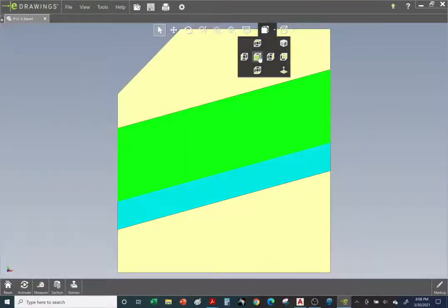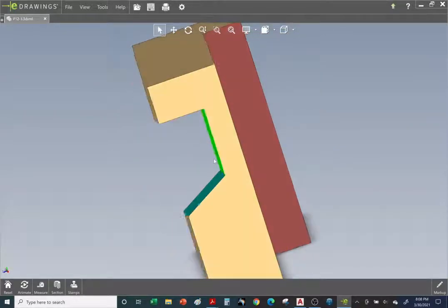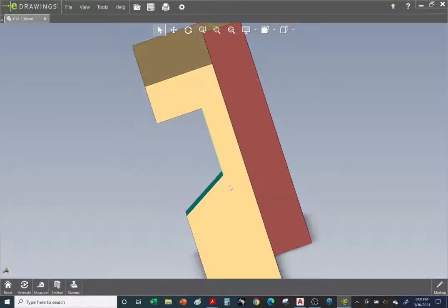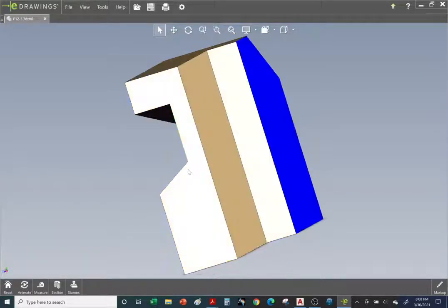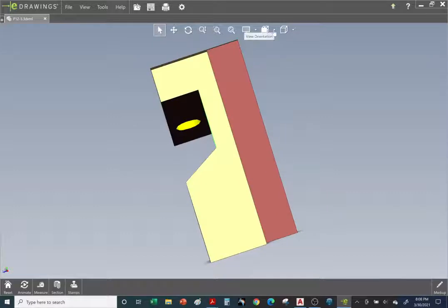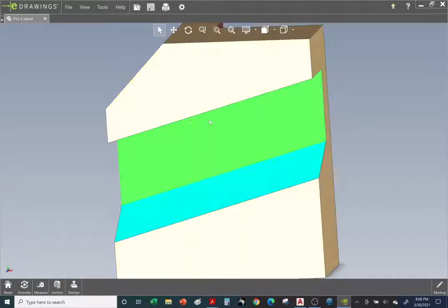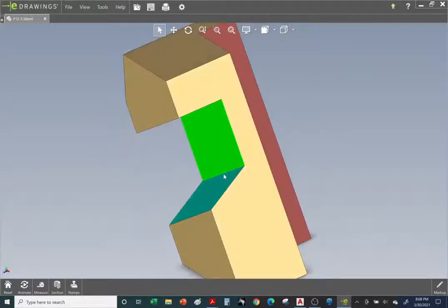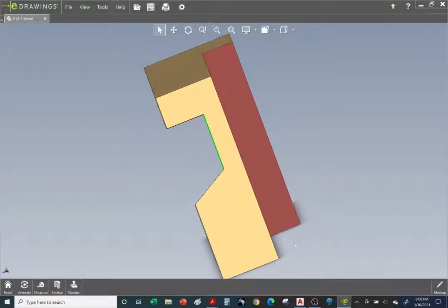Let's go back to the front view. And we have the auxiliary view. So we're now looking down the slot. Okay, so this is the auxiliary view. Notice this is at a different angle, right, versus a right side view. This is what the right side view looks like. But instead, we're going to go with respect to the angle of the slot. So it looks a little different, right? As you can see, the bottom here looks different.